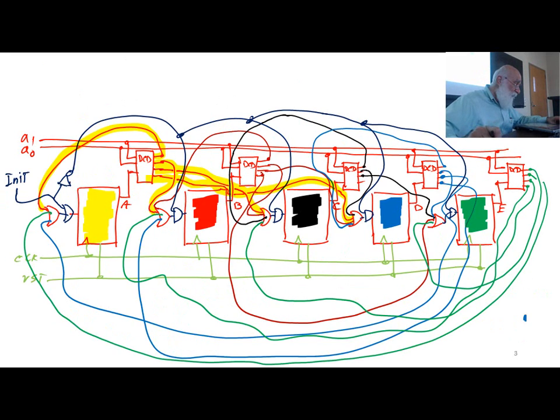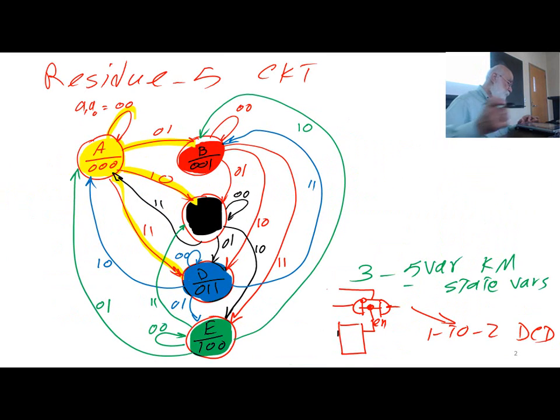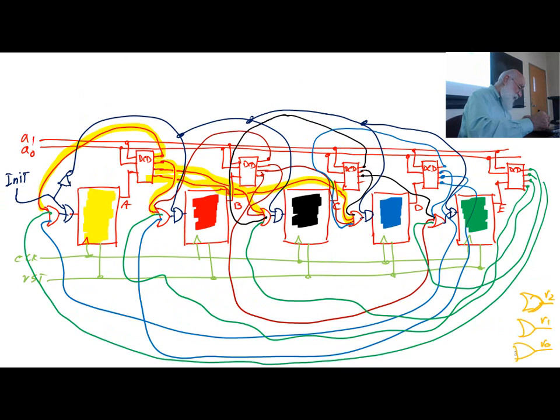And finally, what I need to do is to create my outputs. Okay, I have 3 outputs. R2, R1, R0. I would probably not do the outputs. Oh, by the way, these are OR gates, not. R0 is 1. R0 is 1 when I'm in states B or D. So this is the output.